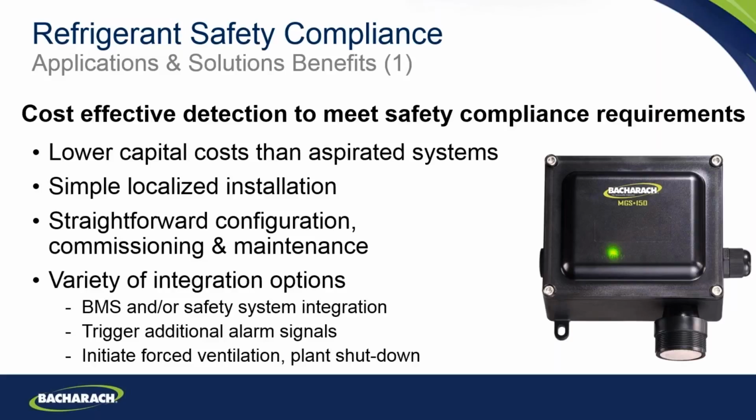The triggering of additional alarm signals can be driven from the refrigerant detection instrument, and in line with some of the refrigerant safety regulations, they can also be used to give an output to initiate forced ventilation, to shut down a plant if necessary.